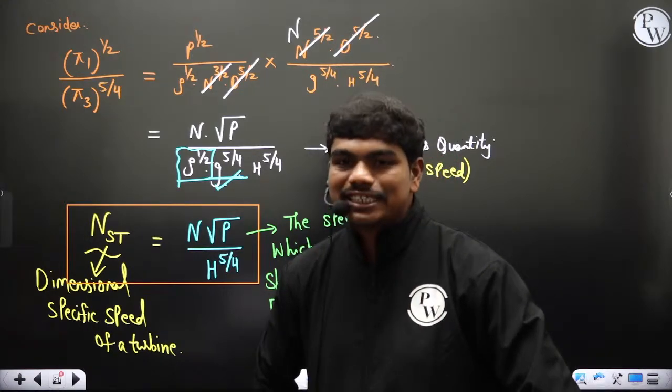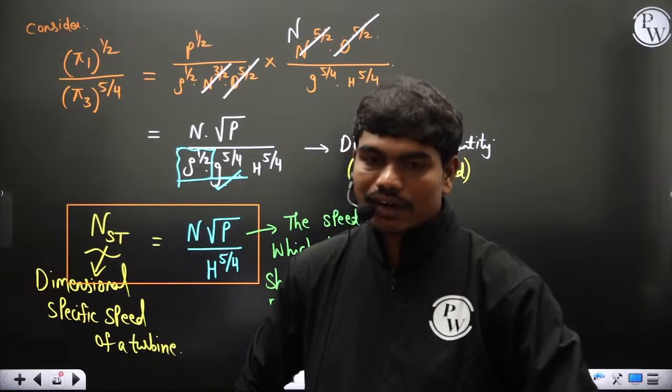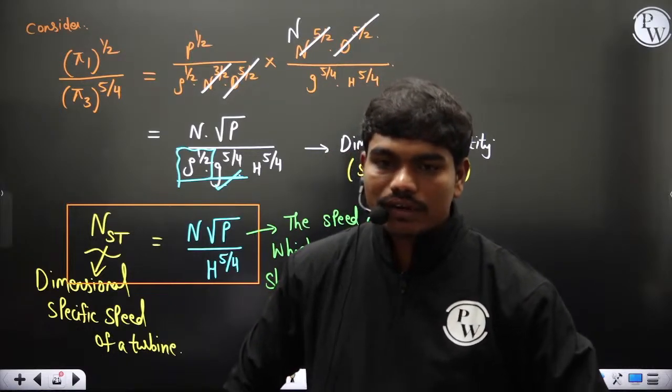I'll discuss at least the Pelton wheel in detail, because for Francis and the others, anyhow, the same velocity triangles will hold, but beta 2 is 90.